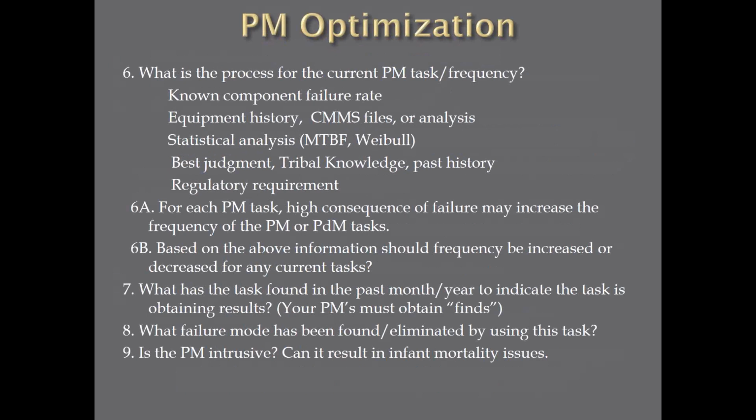So I remember back in the early days when I became a maintenance supervisor, one of my maintenance guys would come in and he would have a stack full of PMs, and I'd ask the question, what did you find? There'd be a stack of 20 to 50 PMs. Oh, I didn't find nothing, everything's okay. My response to that was, wrong answer. If we're doing PMs, we have to have finds. You can't go through a whole department, a whole area of the plant with a stack of PMs and not find anything. So that's when I started doing my training.